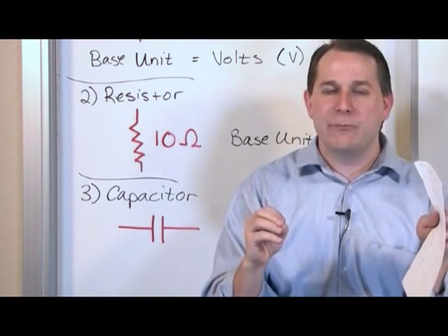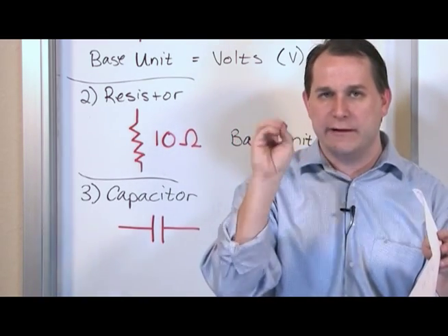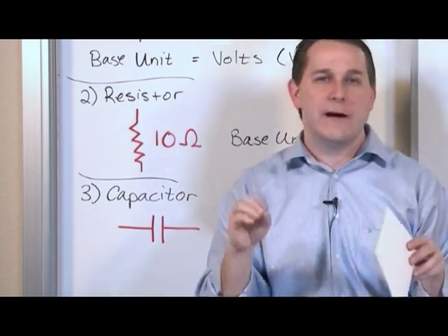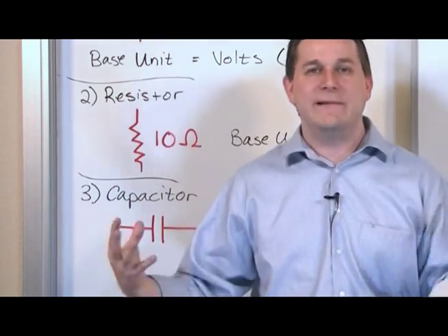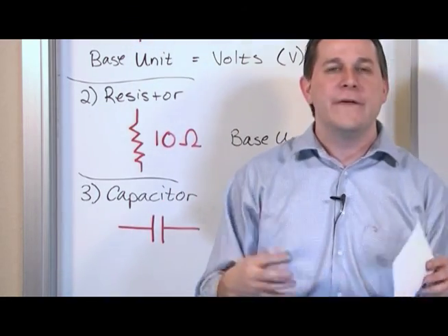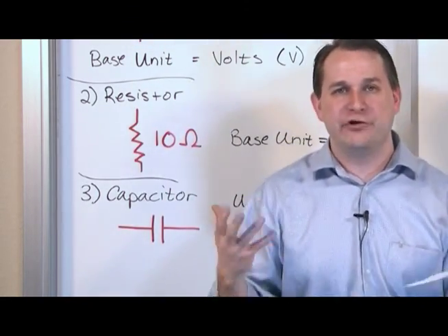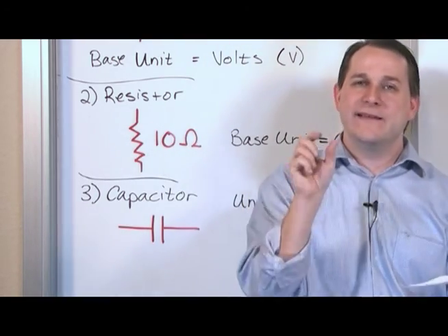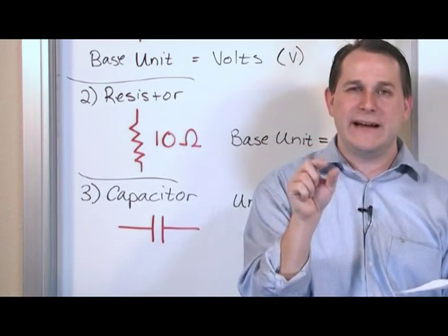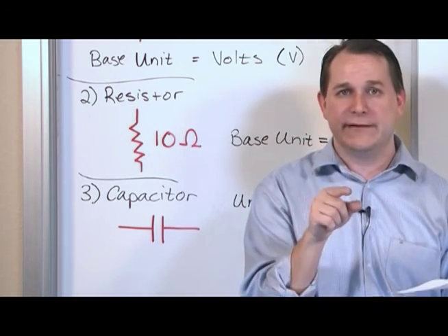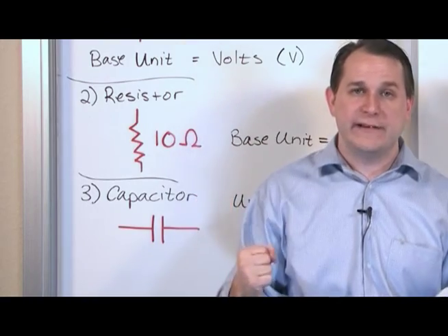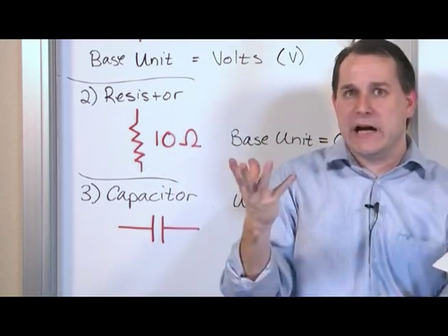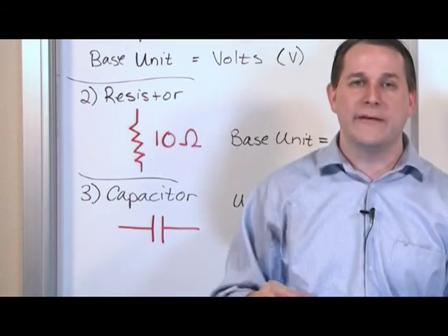And then notice on your camera, it takes a few seconds for that light to come on to tell you, all right, ready to go with the flash. That light takes time to charge up because these capacitors take time to actually accumulate this charge. The reason that you have to accumulate that much charge in a capacitor bank to fire a flash is that the flash bulb is actually a little bit of gas inside of a bulb, basically, and it takes a lot of electricity to jump in there and cause that gas to ionize, for the electrons to jump around and release all that white light.